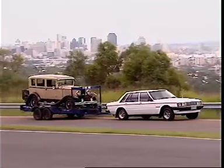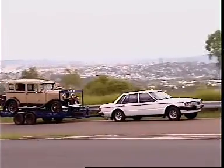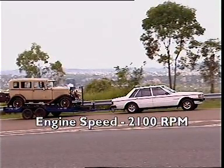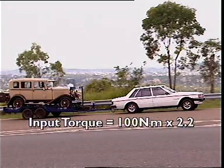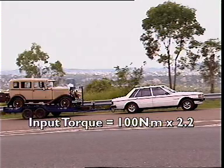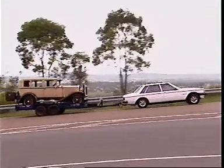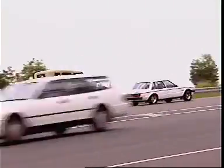Instantaneously, as the vehicle begins to move, maximum torque multiplication occurs. At an engine speed of 2,100 RPM and torque at that speed of 100 Newton meters, the torque input to the transmission will be 2.2 times that value, 220 Newton meters. This multiplication tapers off as the turbine commences to turn and increases in speed.